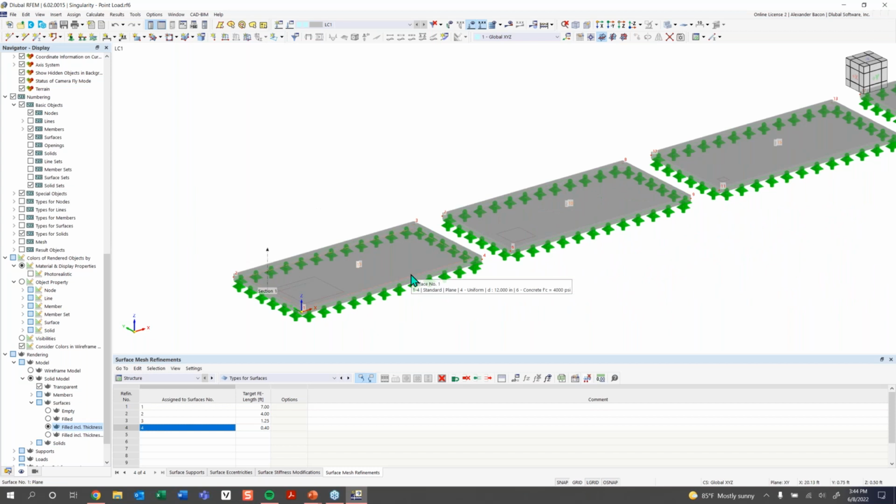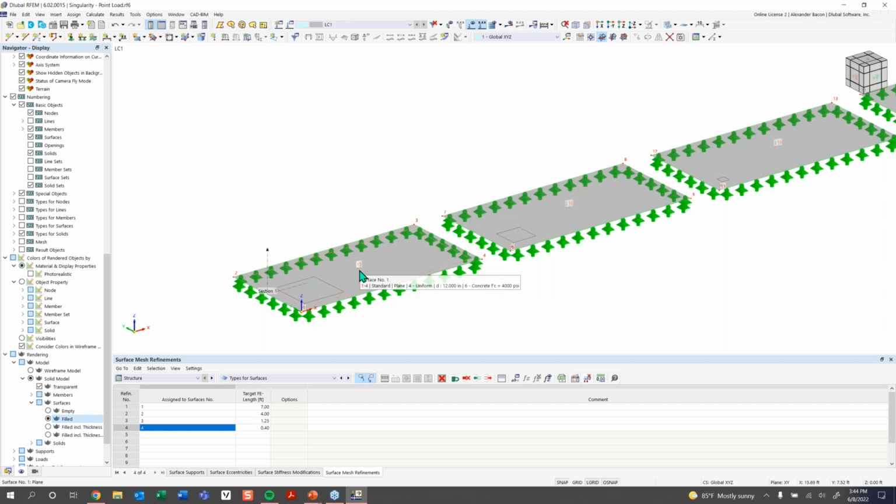And the reason it's good to know where the center line is located is because this is where the surface load is applied. And normally for concrete structures, the forces will propagate from the location of the load through the concrete at a 45-degree angle. So this is always just good to keep in mind that you need to take into account that the loading is going to be applied at the center of the thickness.